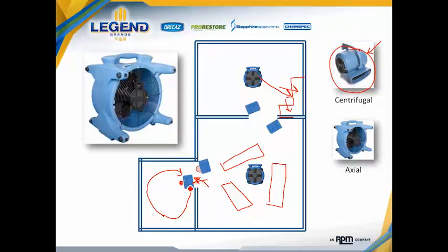So if I went in the opposite direction with my air movement and went this direction around the room, I would not have an intake drawing from the neighboring room. It would be the motor assembly that would be presented with the airflow, not the intake of the air mover. So clockwise, if you're using that centrifugal type, a Sahara type air mover, is critical for that orientation. Counterclockwise rather, simply will not work.